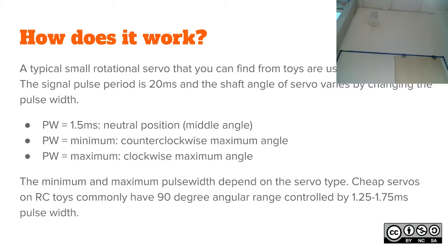But this can range from 1 to 2, which is quite common also. The problem of running it on too short or too wide a pulse is that it can get mechanically stuck if you run it at full tilt on either of those edges. Cheap servos do that.